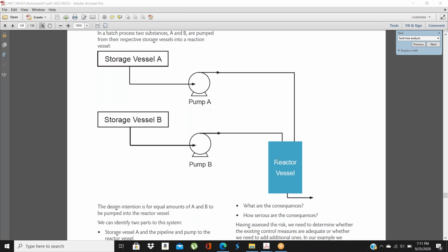So to control the temperature of this reactor, we will install a sensor which will monitor the temperature inside the reactor. To control it, we can install a water jacket or some other chilled water cooling system, a cooling jacket around the reactor, which will take the heat from the reactor.